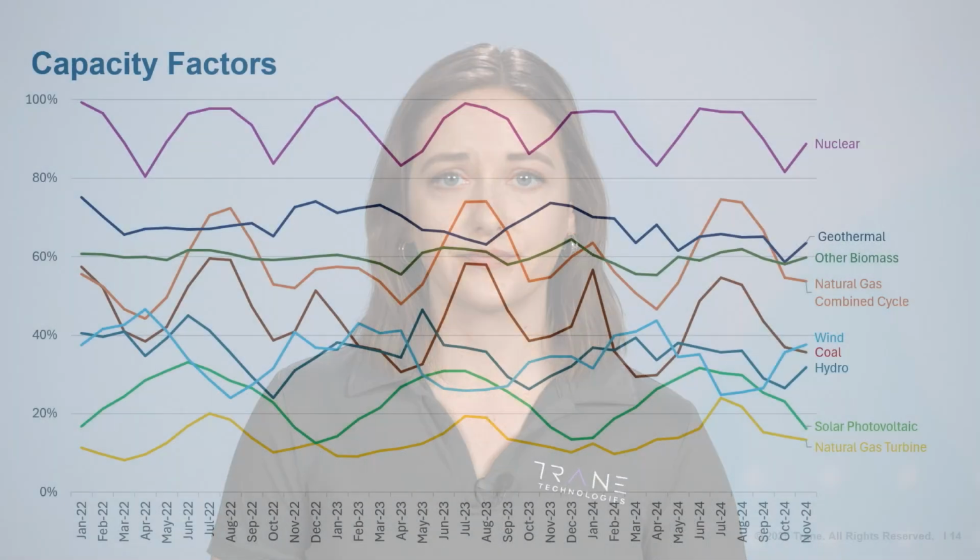Now that we know the basic characteristics of energy generation resources, let's explore how those factors impact how and why various resources are used on a grid. There are two concepts that will help demonstrate the operational impacts of resource characteristics: capacity factor and baseload versus non-baseload designation. Capacity factors describe how much electricity a source has actually generated relative to theoretical total possible production.